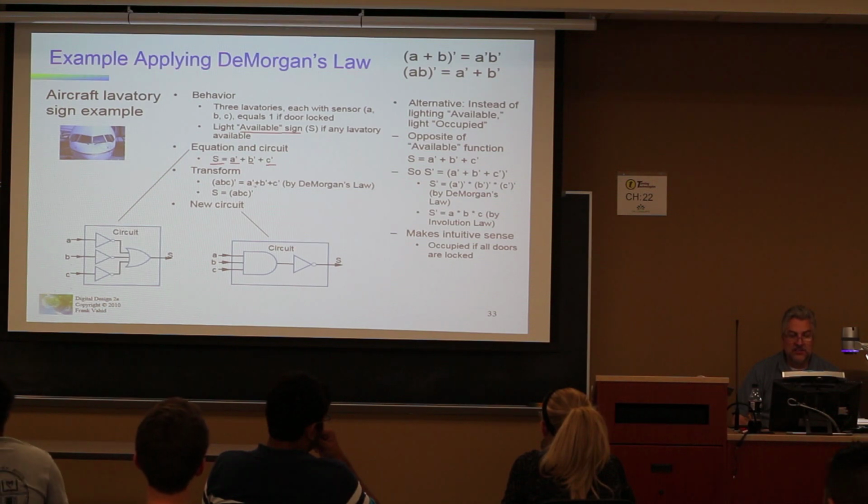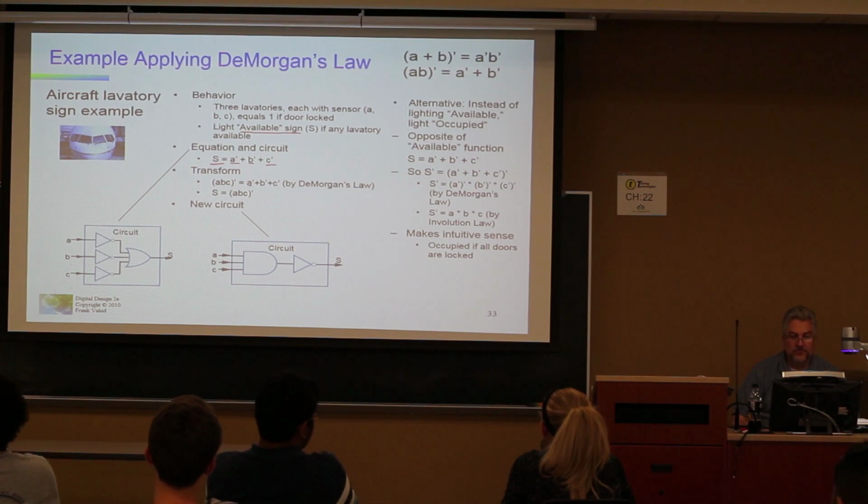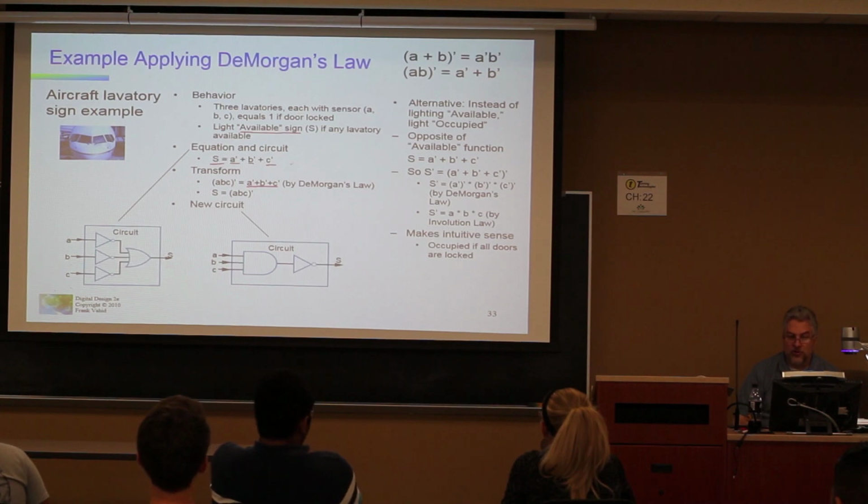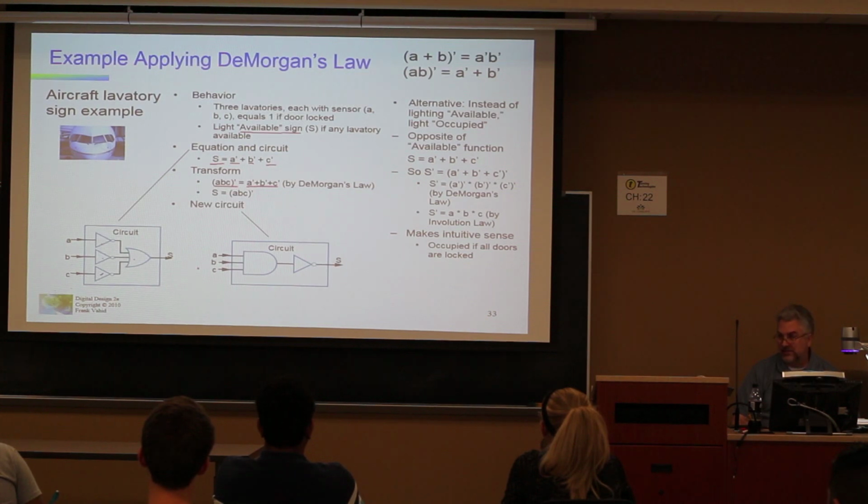And since this is by De Morgan's law, as we saw up here, if we're having the complement and we're all ORing them together, it's the same as ANDing them and then taking the complement. And what's the difference? Well, 1, 2, 3, 4 gates versus 1, 2. So you have a bit of a savings there.